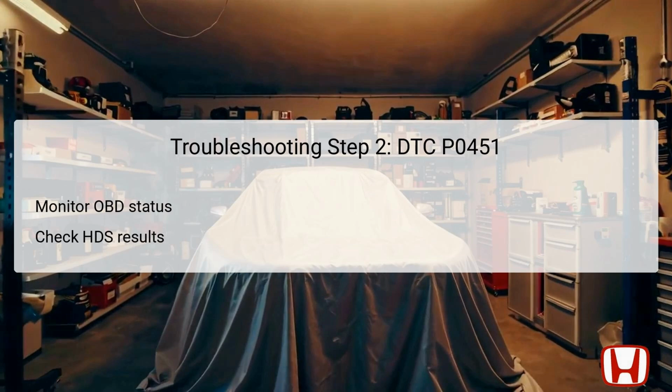Alternatively, if the status is passed, this suggests that the sensor and circuit are currently operating correctly. In cases of not completed, it is essential to keep the engine idling until the status can be reliably assessed, ensuring that all conditions for testing have been met to reflect accurate results.